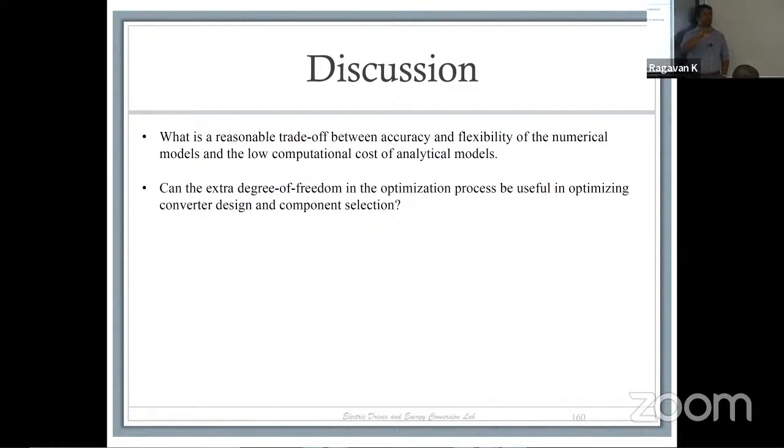Because you're not only talking about the motor, you're talking about possibly controlling the current, where you might want to see a current waveform that is very sharp. For SRM, you're looking at a current profile that has a reasonably effective shape. What if you had a shape which has a U shape or something different that is very unique? Does your DSP have the right switching frequency capability? Does your sensor feedback give you the right sampling time? Do you have the right bandwidth? Those questions need to be addressed whenever you are talking about designing a closed form solution.